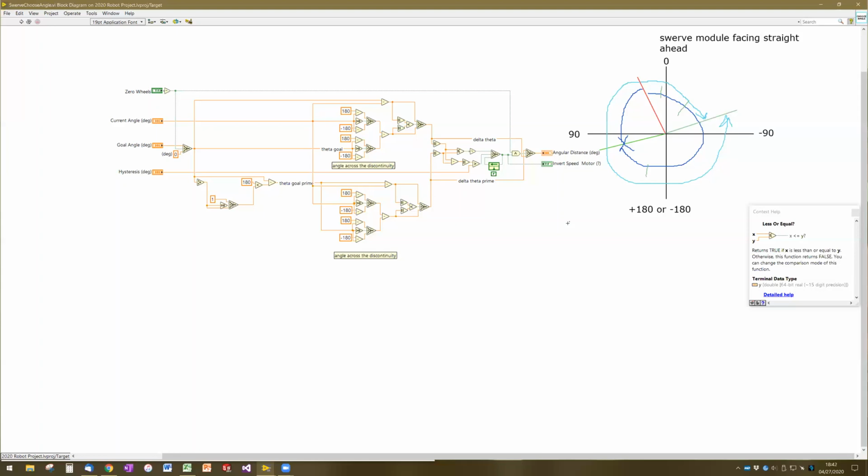And so that meant that the behavior of the system could actually be a little bit different depending on whether or not you picked up a ball off of the Alliance Station wall and then backed up to the initiation line versus if you grabbed the ball in the trench and drove forward to the initiation line. Those two actions would actually, even though you ended up at the same point, result in different cowl angles using the targeting computer. And so that was one of the things that made the targeting computer kind of challenging.